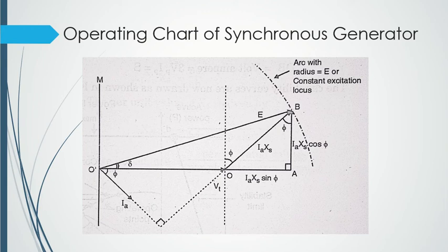So we will only consider the voltage drop across the load, and then we will consider the drop because of the reactance, right? The IX drop. This IX drop as well, we divide into two components, the sinusoidal component and the cosine component, or you can call it real component or imaginary component if you are into mathematics, right? So let me first quickly give you a glimpse of how we plot this phasor diagram. If you have attended the previous lecture, it would be a cakewalk, but either way, let's get done with that.